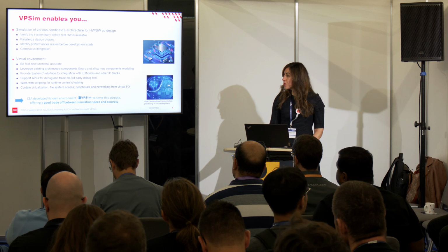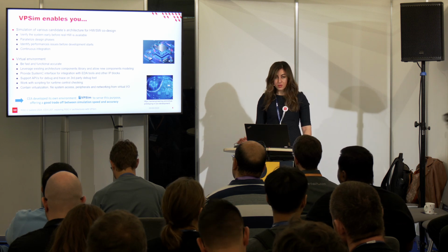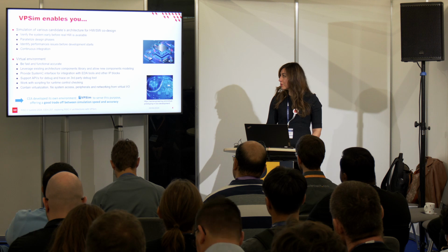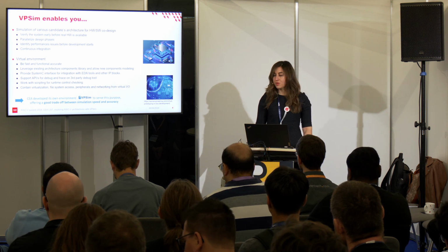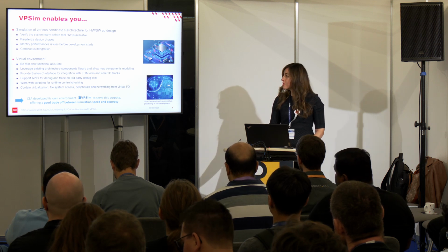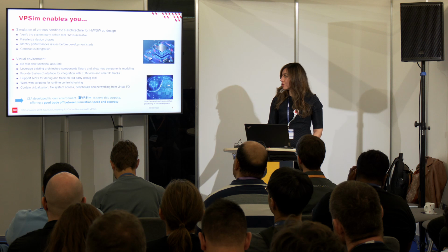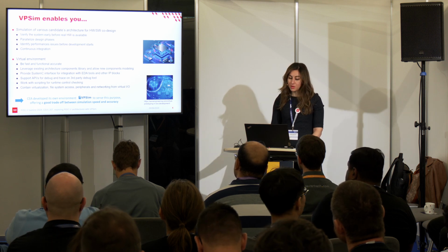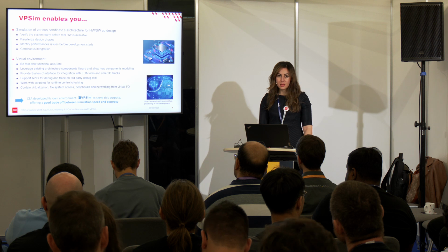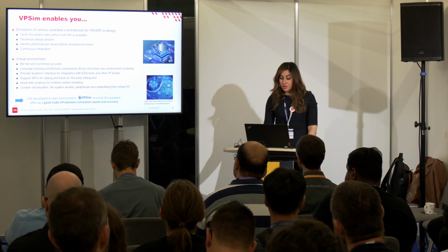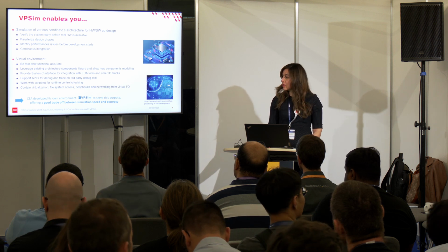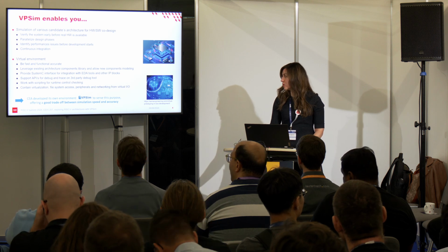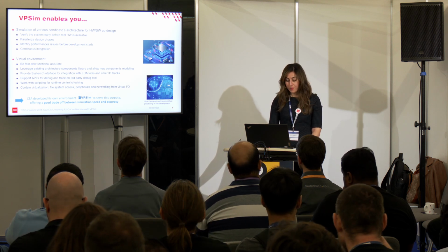To do that, the virtual environment should be fast and functionally accurate, leverage an existing architecture component library and allow the integration of new ones, provide a SystemC interface for integration with EDA tools, support various APIs for debug and trace on third-party debug tools, work with scripting for runtime, and contain virtualization, file system accesses, peripherals, and networking from virtual I/Os.